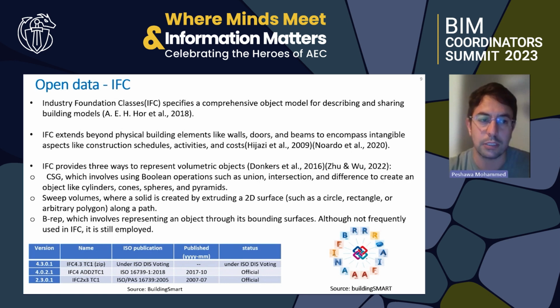The first one is CSG, which involves using Boolean operations such as union or intersection to create new objects, or using sweep volumes, where we have a 2D plan and 2D object, and we are just extruding that 2D object into a 3D, or maybe using BRep, which is a boundary representation. It can also be used for representing objects in IFC.